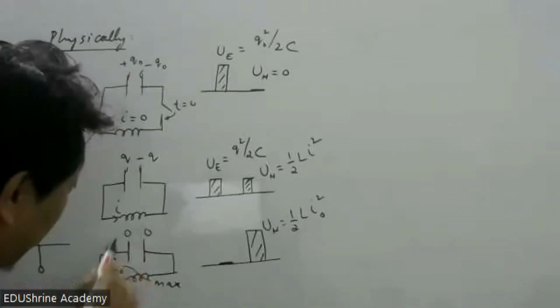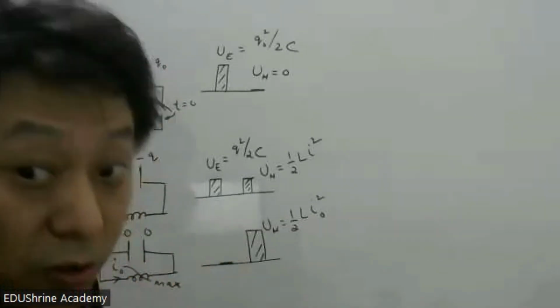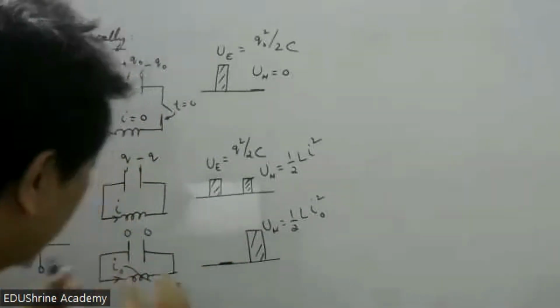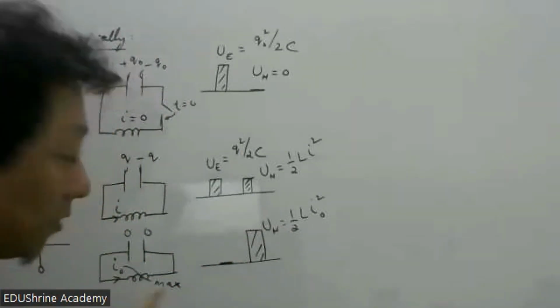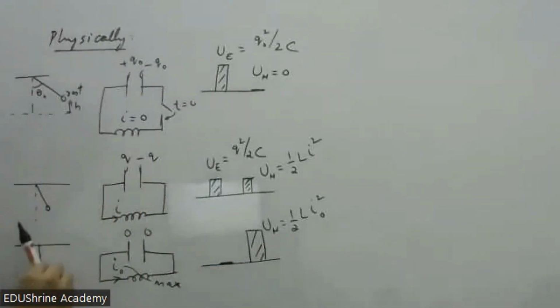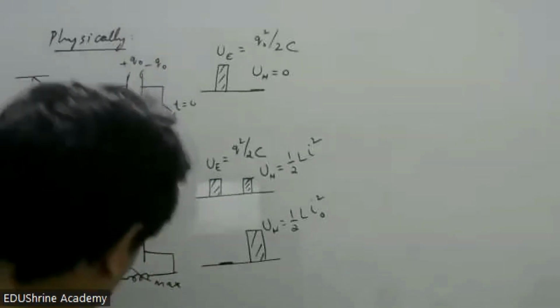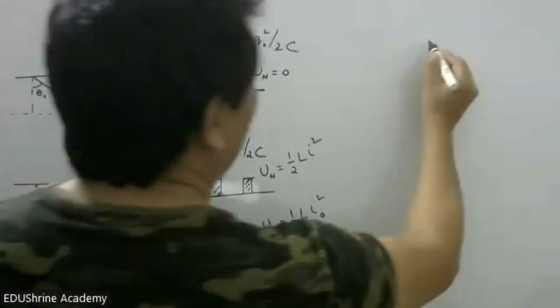So this driving voltage is not there. Current right now is maximum. So current wants to decrease to zero now because there is no voltage. But the inductor will not allow it to decrease instantly. Just like this mass will continue, this current will continue. So as this current will continue, see next how it will look.